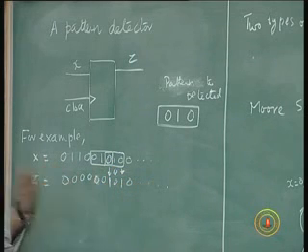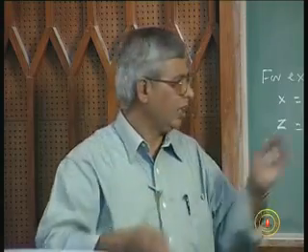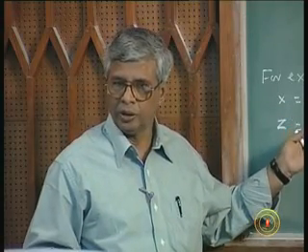And there may be any number of 0, 1, 0s. Wherever there is a 0, 1, 0, whether as an independent pattern or an overlapping pattern, corresponding to the third 0 of that 0, 1, 0, I need an output 1 for 1 clock period. That is the problem statement and an example sequence, sample sequence, input and output.